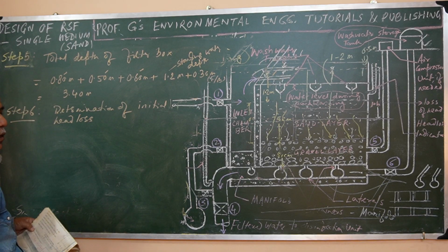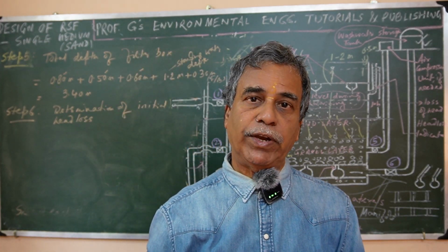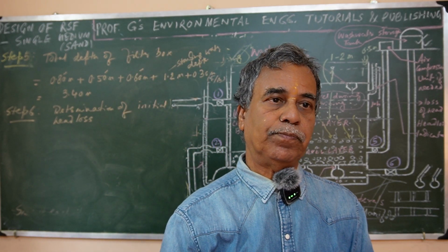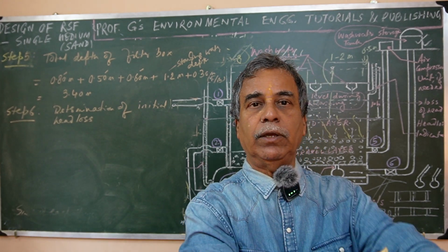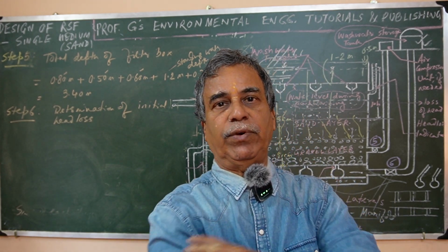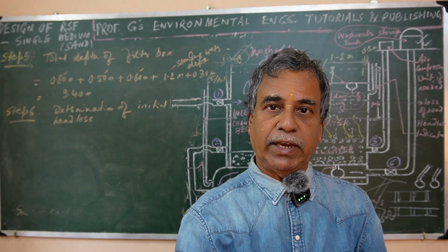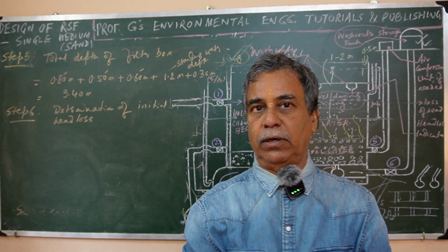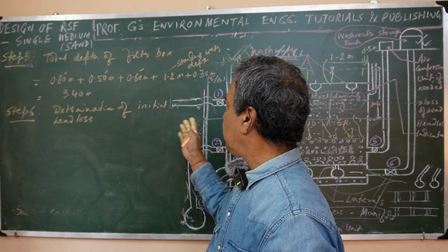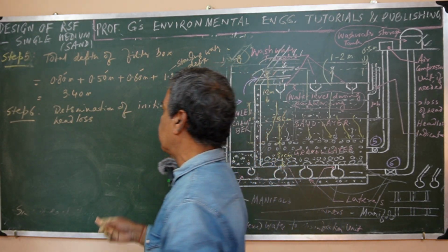We discussed how to find out the initial head loss, that means immediately after backwashing, when the filtration cycle has started once again, this initial head loss should not exceed 0.3 meter or so.